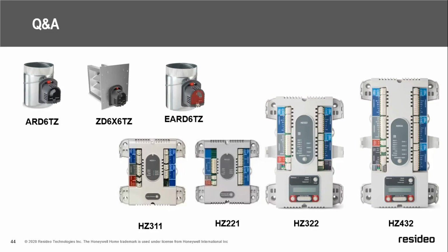On the initial startup, if you've got that connected to the DSBK terminal, we will power down the dehumidification terminal. We're lying to the air handler. It may be the coldest, driest day of the year, but we're pretending that it's a humid day by powering it down to 65 to 70% of its normal RPM until we have more than one zone calling.